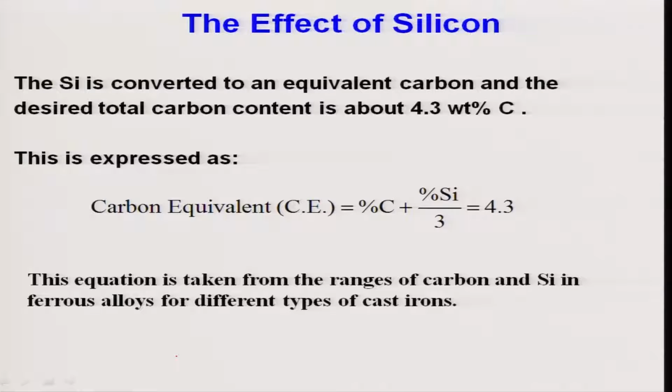So, in a nutshell, this iron with 2% silicon and carbon phase diagram is a pseudo-binary phase diagram. Why pseudo? Because there are 3 components, iron, silicon and carbon, but we are plotting a 2-dimensional plot like a binary phase diagram. That is why it is called a pseudo-binary phase diagram.